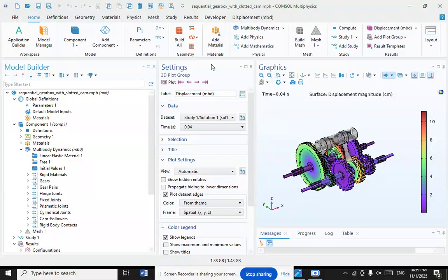to the shaft. Unlike some other types of clutch, such as the foot-operated clutch of a manual transmission car, a dog clutch provides a non-slipping coupling and is not suited to intentional slipping. And what about the synchromesh? In order to provide smooth gear shifts without requiring the driver to manually match the engine revs for each gear shift, most modern passenger car transmissions use synchromesh, also called synchronizer rings, on the forward gears.